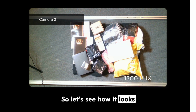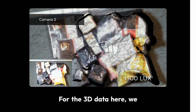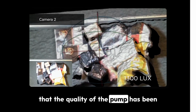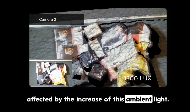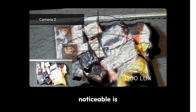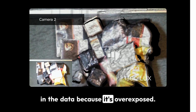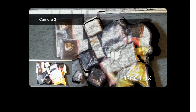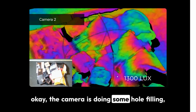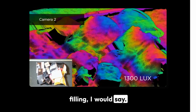So let's see how it looks when it comes to the 3D data. For the 3D data here, we can also clearly see that the quality of the point cloud has been affected by the increase of this ambient light. What's very noticeable are the holes that we get in the data because it's overexposed, and if we remove the color again, we can clearly see that the camera is doing some hole filling, but it's not very accurate hole filling, I would say.